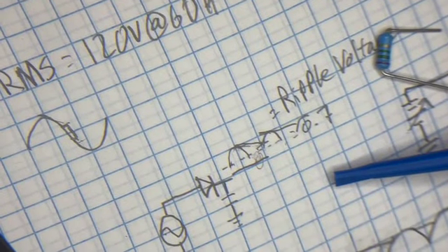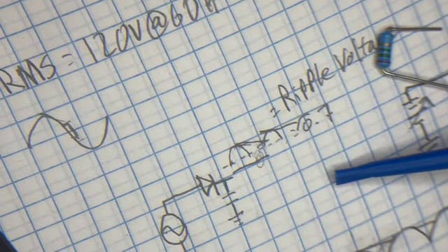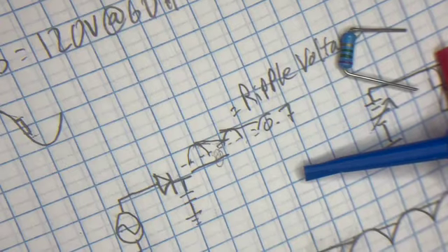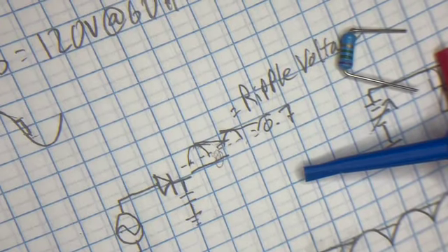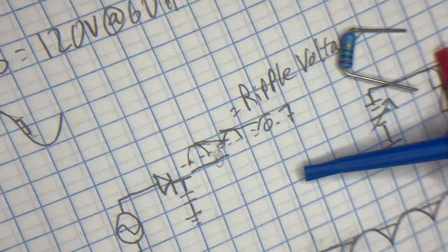And I'm going to do a little bit of a calculation to determine what size of resistor I should use for this diode. Now, to really do this, I've got to look at the forward voltage of the diode and its maximum current rating. So I'm going to go to the data sheets and look up this particular diode.